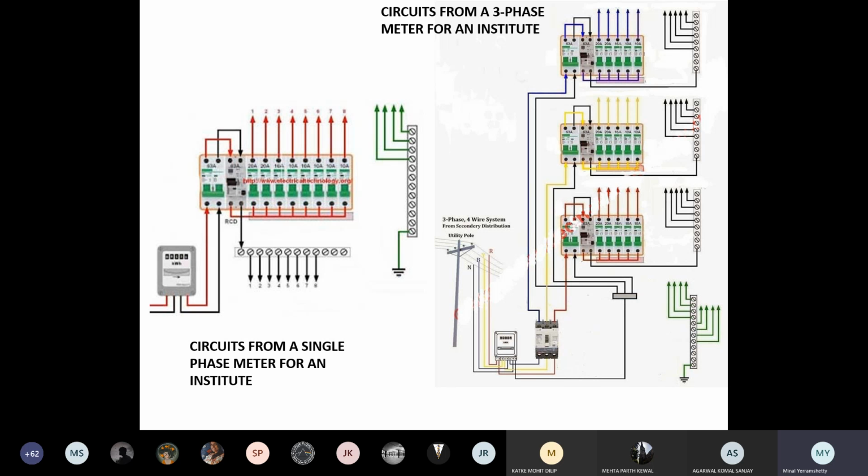So then what happens is from the cutout, it goes to the bus bar, or it goes to the meter because here we don't have to do any separate metering. So it just goes to the meter. Meter mein jaake it starts metering, and then I need to distribute the wire. Right? I don't need to distribute it before that.